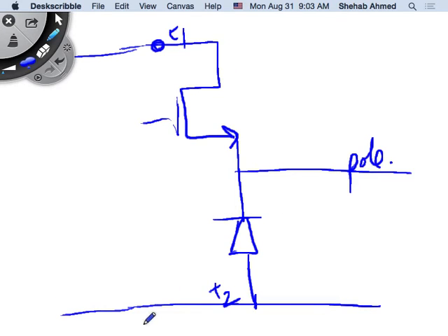But for example, in this configuration, I have one pole and 2 throws, okay? And of these 2 throws, either the top device is on or the bottom device is on. I cannot have them both on. If I have them both on, it's a short circuit condition. It only happens during this transitional stage where there's reverse recovery. Forget about that. That's not important for power electronic circuit operation. For loss, yes, it's important.